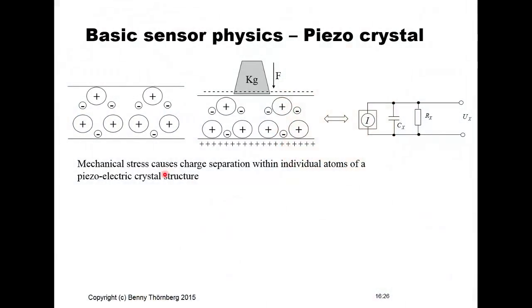If we expose a piezoelectric crystal to an external force, there will be a change of the charges inside the crystal material such that we are able to measure a voltage on its surfaces. Have a look at this drawing where you see the internal crystal structure, and there is a force that is compressing the material in such a way that you can view it as an accumulation of negative charges on one surface and positive charges on another surface, allowing us to actually measure a voltage over this piezoelectric crystal as if it was a charged capacitor.